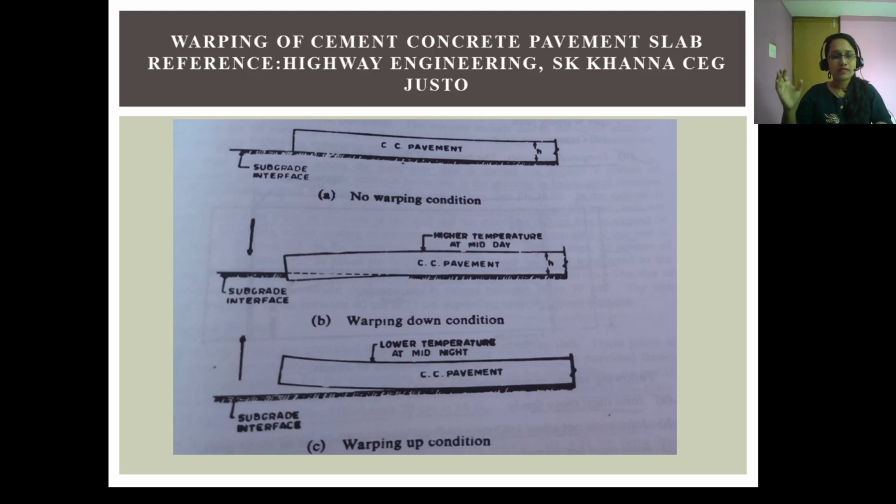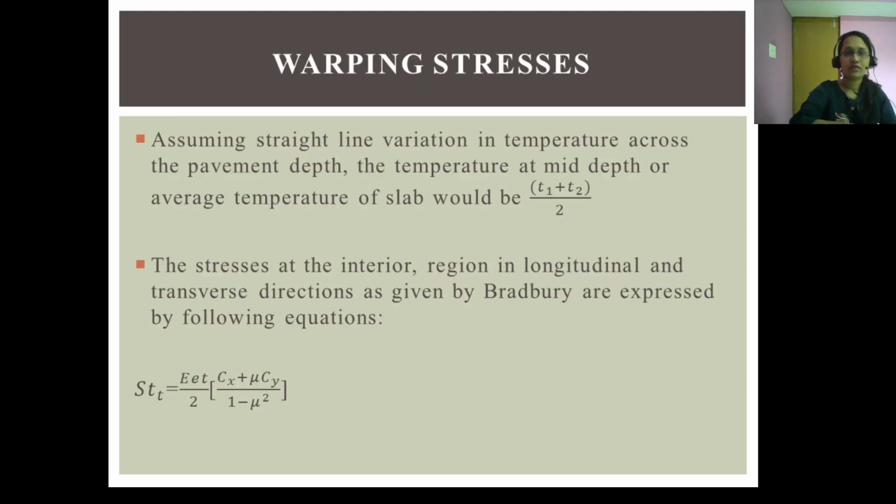Now, to minimize the temperature stresses in the pavement slab, expansion, contraction and warping joints may be provided transversely across the full width of the pavement. Okay, so next we will see the warping stresses.